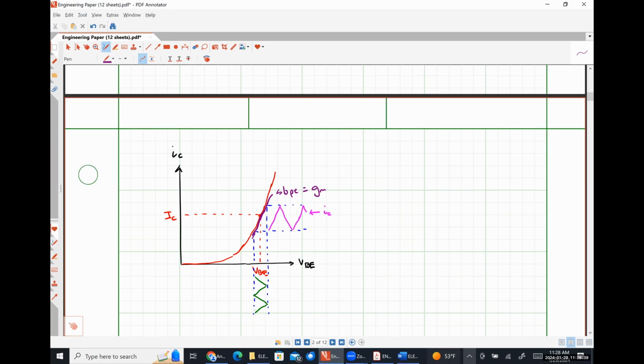That being said, supply voltages and all of that kind of stuff might have noise on them, which will wind up causing perturbations as well. But for the intents and purposes of what we're talking about right here, using the device as an amplifier, we are supplying the perturbation. That is something that we have control of. So we are purposefully pushing the signal slightly away from its DC operating point in order to achieve some form of amplification.